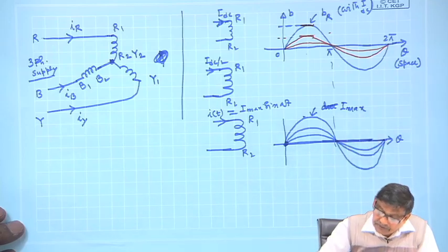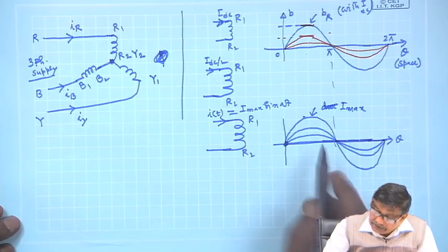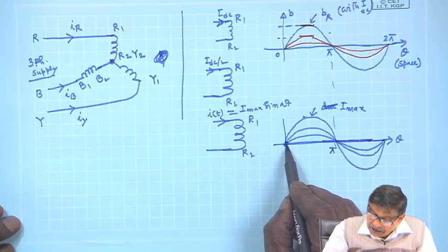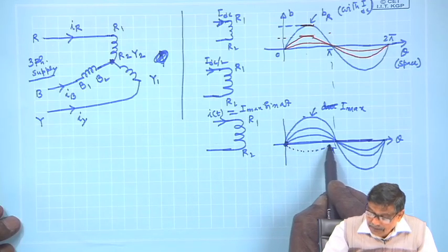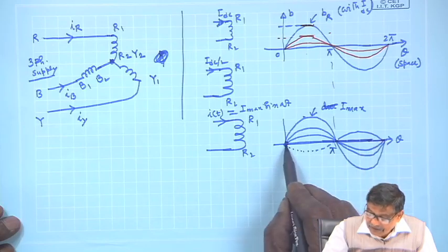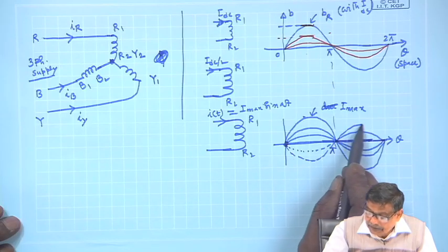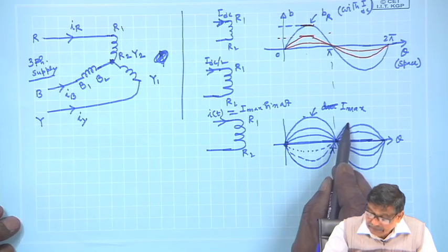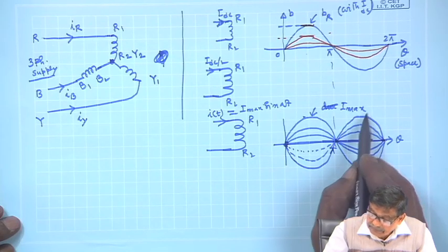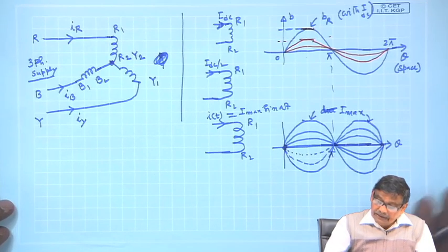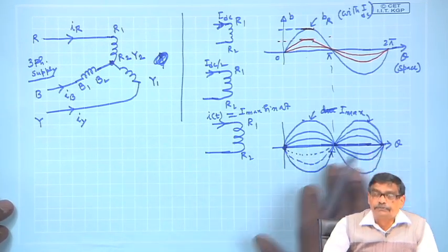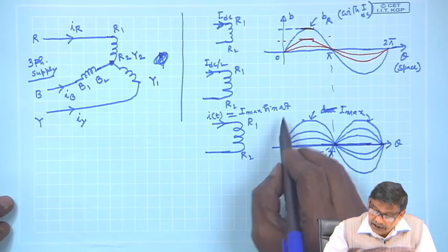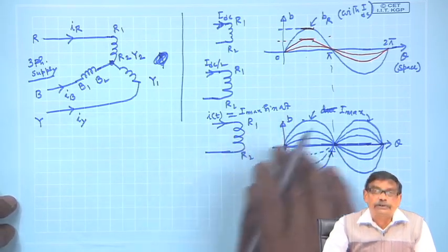And notice this current will become negative sometimes, then the polarity of B will also be negative, depending upon the magnitude of the current. Getting it? So, this will be the kind of wave of MMF distribution, flux density distribution along the air gap of the machine. We will continue with this. Thank you.